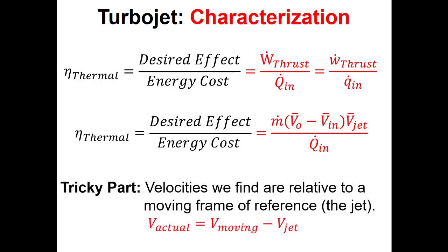One of the tricky things when we're dealing with these turbojet problems is that we'll often be using a moving frame of reference, right? When we're talking about these turbojets, it's kind of like we're a crazy person that's standing out on the wing of the jet as it's moving. So even though the air might be still, it feels like it's whipping into our face because we're standing on top of this plane wing, right? Probably not the safest place to be, but that's our moving frame of reference.